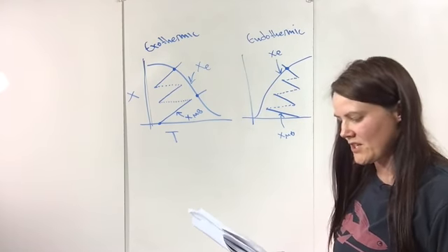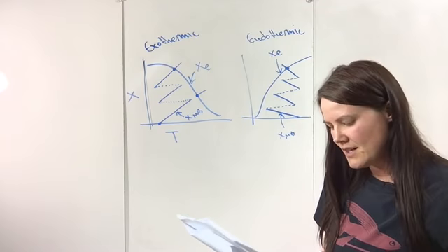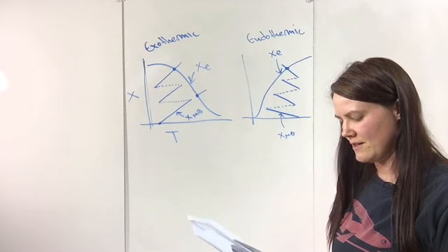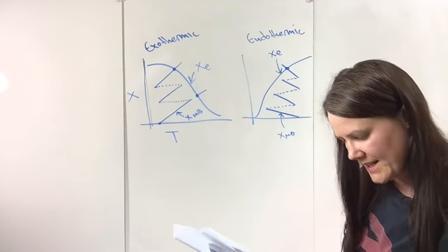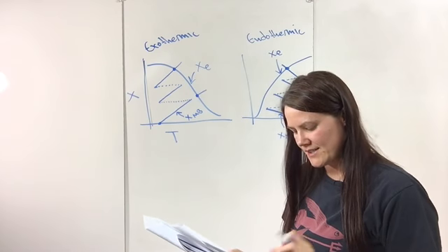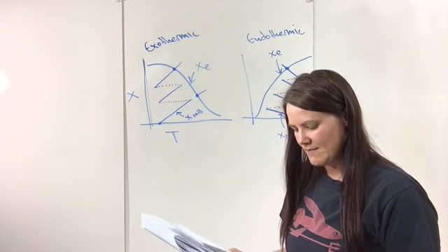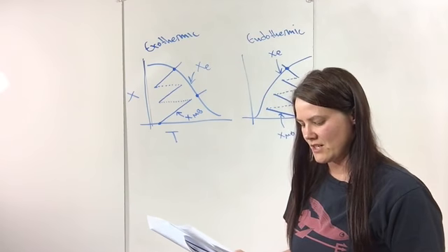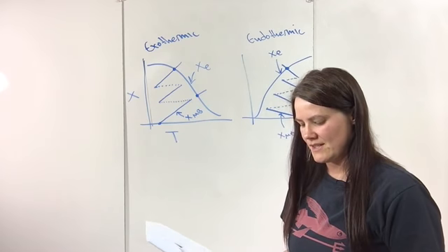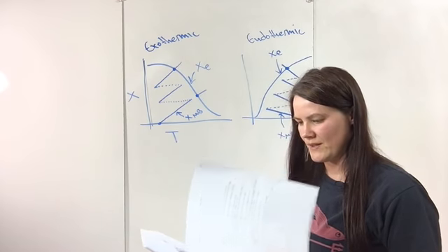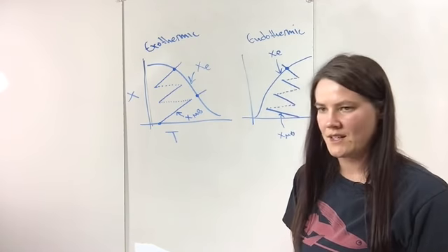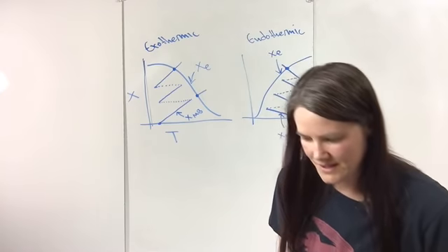And so just make sure you're aware what happens to the equilibrium conversion depending on if your reaction is exothermic or endothermic. And then he has a CSTR, adiabatic or with jacket equations, calculation of multiple steady states, and PFR, finding temperature and conversion with volume of the reactor. And for those, you'll usually need an ODE solver because for the CSTR, it's probably algebraic, but for the PFR, you're going to end up with two coupled ODEs.